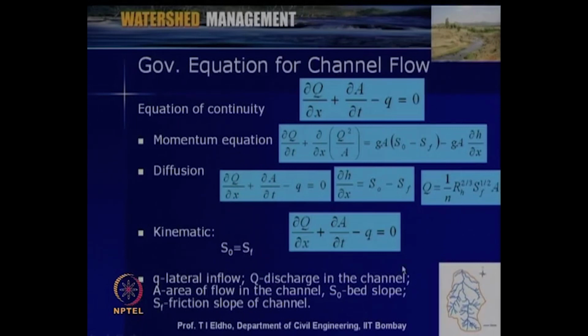So, as far as channel flow modeling is concerned, the governing equations are defined. Then the various forms of governing equations, like Saint-Venant's equation, the dynamic wave form, the diffusion wave form, and the kinematic wave form, one of which we can utilize, and the boundary conditions and initial conditions are defined. So, our mathematical model is ready.